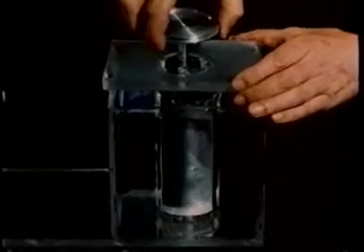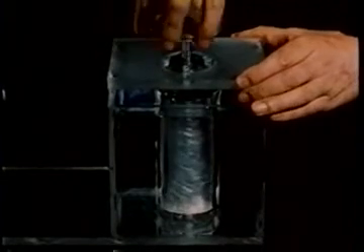Not all flow instabilities result in a new unsteady flow. For example, let us look at the flow between two concentric cylinders. The inner cylinder turns, the outer cylinder is stationary. We have put flakes in the fluid to make the flow visible. Turning the inner cylinder at an angular velocity less than a certain critical value, the flow is stable. Increasing the angular velocity to above critical, bands appear in the flow.